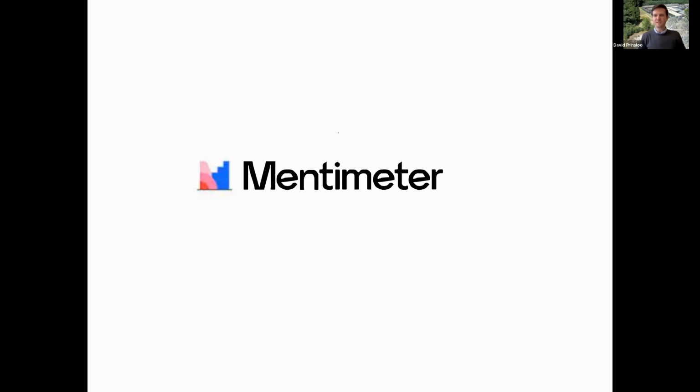So just before the questions, the recap in Mentimeter, we looked at radiation patterns, and we also looked at the fields radiated in the far field. But what I want to look at next are the radiation quantities that you can define for the antenna. And there's one very important quantity that we need to look at first before we can get to the definitions of gain, for example, that is typically used. And this definition is the radiation intensity.